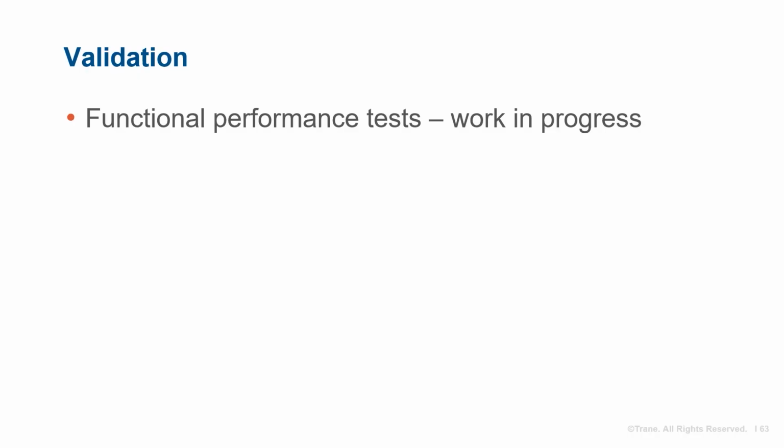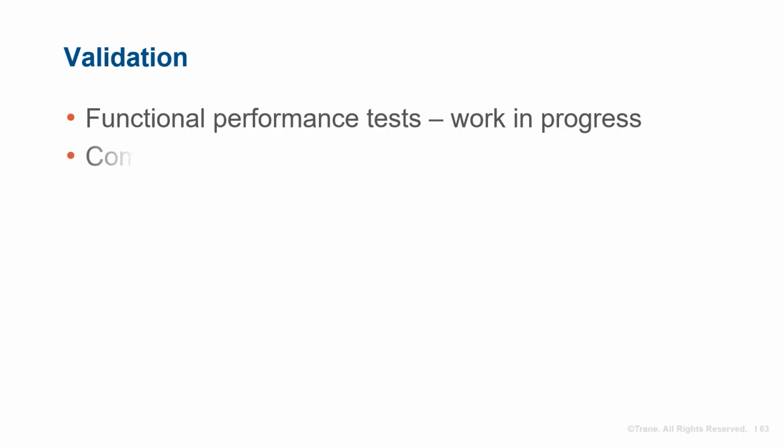There is work underway by the Guideline 36 Committee to create functional performance tests to aid in validation of the manufacturer pre-programmed sequences. In addition, functional performance tests will likely be created to validate sequences once installed. Until these are completed, it's best to work with your manufacturer or manufacturer's representative to understand their implementations.